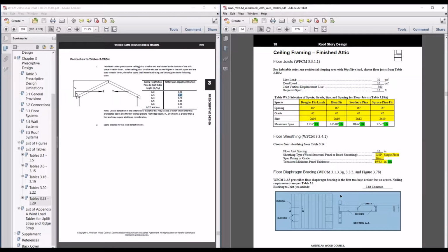That, you may have already figured out then, is that the diaphragm values we're assuming are unblocked diaphragms. So this blocking, just above 130, just gives us a little bit of added stiffness to get some loads into the shear walls. So again, the commentary gives you background for all the assumptions, including the diaphragm capacities that we assume in this document.